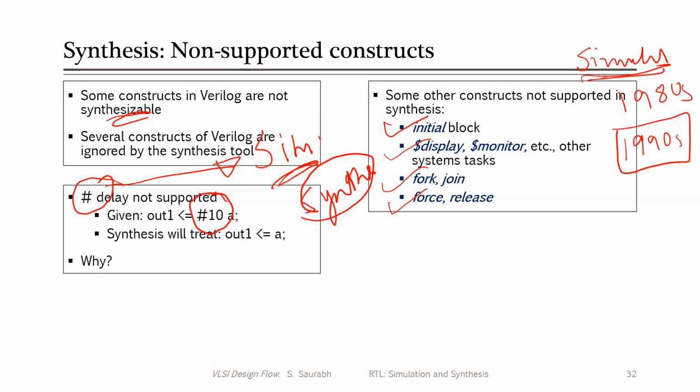Why is it difficult to achieve, say, an exact delay in our circuit? Any answer? Sir, process variation. Yes, one of the reasons is process induced variation. So even if you design for, say, 10, because of the process variation, it will become maybe 11, maybe 9 or something, right?